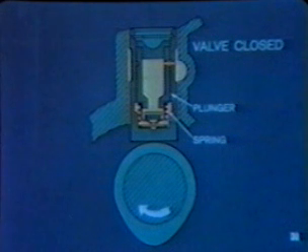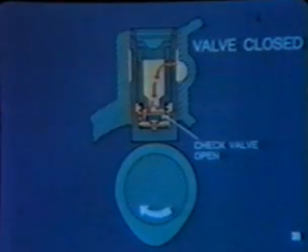When the lifter is on the low part of the cam, the engine valve closes. If there is clearance in the valve train, the spring will push the plunger to take it up. At the same time, pressurized engine oil flows through the body and plunger and past the check valve to fill the chamber under the plunger as the plunger moves upward.